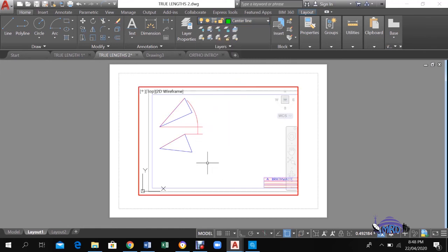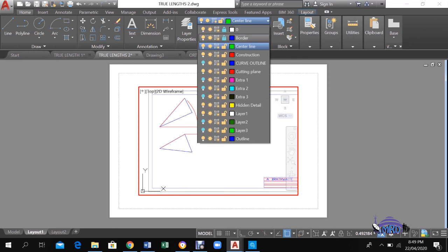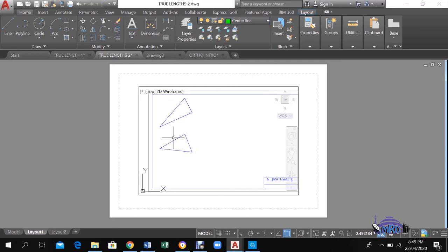If we look at the revolution method being applied, I've highlighted the lines now in red. You will know that you will put the compass at the lowest corner. You will scribe the arc, come into horizontal. You will drop a line down, and you would have a horizontal intersecting that line from the plan view. So then the true length will be a line from that intersection down to here. I have not put in the true length as yet, and I will take my time in putting in the true lengths. I will put in all the true lengths basically at the same time. So just remember, that's how the true length is found for side number 1.